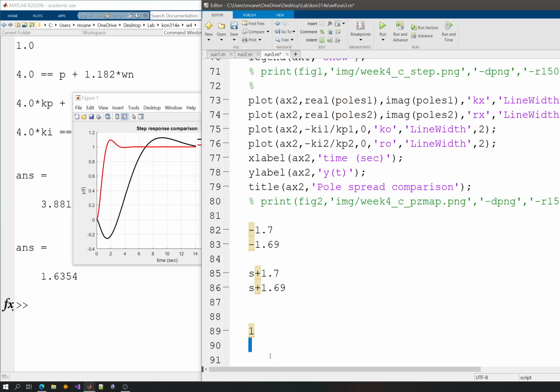By that I mean you shouldn't have a disturbance or noise, since you are not able to reject disturbances if you have an open loop, since you are not looking at the output. What open loop means is that I'm guessing what I should apply to the system by looking at its mathematical representation and taking the inverse. This means that I'm guessing my control input, and I'm not checking the output if it's what I was expecting.